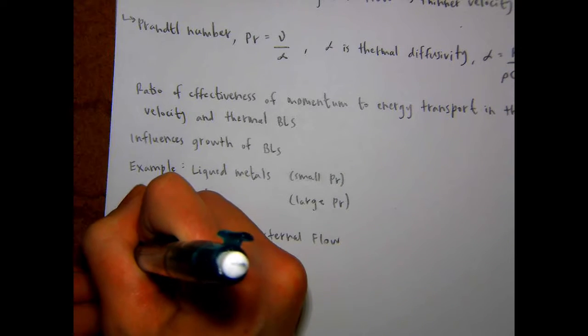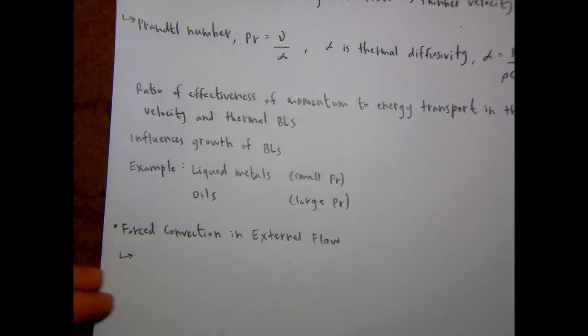So what makes external flow simpler than another type of flow, for example, internal flow in a pipe, is that the boundary layer isn't constrained by any adjacent surfaces. So you just have the boundary layer develop naturally, and the flow velocity and temperature just recover to the free stream values and you don't have to consider how close you are to another solid surface. It's just one solid surface with the boundary layer developing naturally.